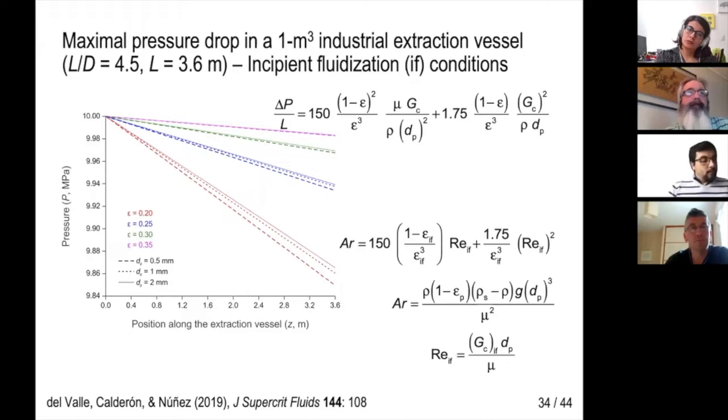The top pressure drop estimated using the Ergun equation corresponds to the imminent fluidization condition. Under imminent fluidization conditions, the pressure drop weighted by the cross section of the bed equals the weight of the material loaded in the packed bed, allowing the maximum superficial velocity of CO2 rising along the vessel to be estimated.